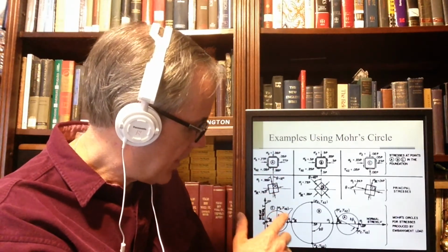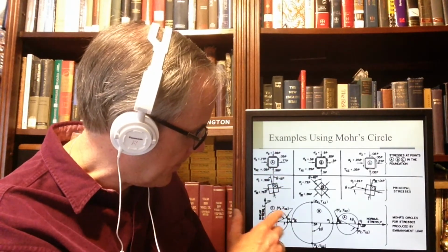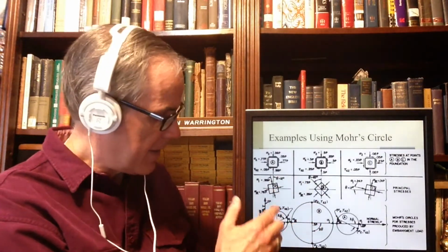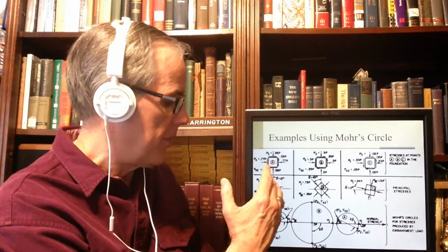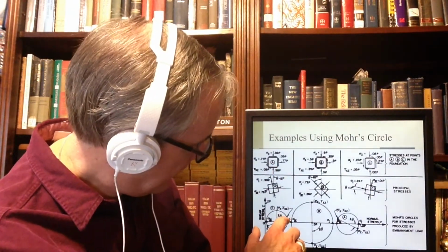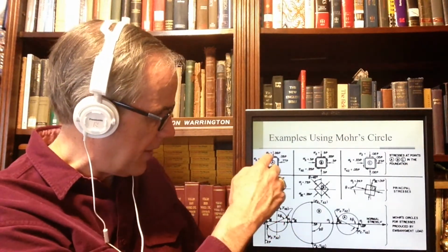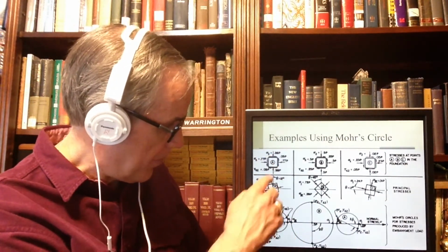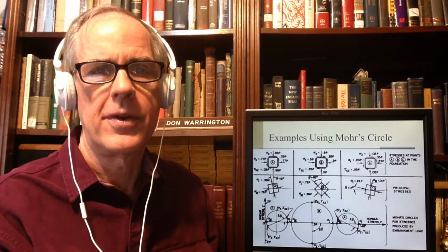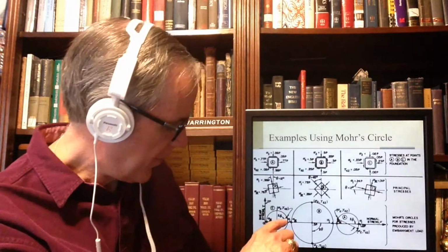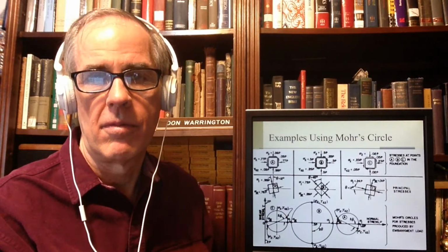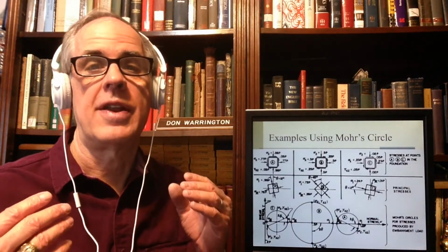And then this is how they draw it out on a Mohr circle, this way. And notice that for every theta that the little element actually rotates, it's 2 theta on the Mohr circle. You get the Mohr circle point. This point and this point are the stress states up here, and this point and this point are the stress states there. So therefore, there's not much difference. This is fairly close to the principal stress, so there's not much difference. That's the first state.